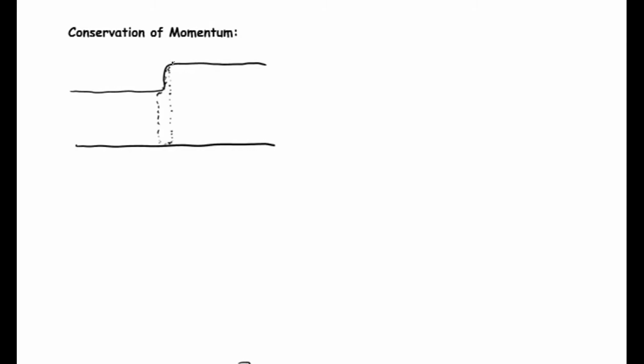And when we do this, just remember this width here is infinitely small, really, across that wave, or it's very, very small. So the reason we didn't ever do this before is because we wanted to avoid the shear force. Well, since we're making this very, very small here, we're going to assume that shear force is negligible anyways, and so it's okay to do this.